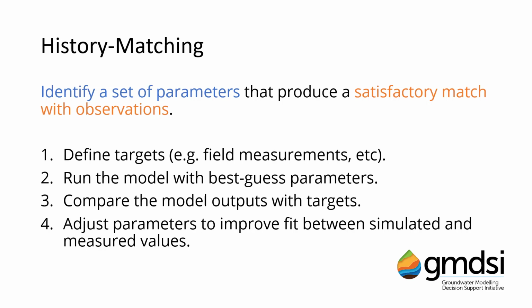and repeating the process. In essence, this is what you would have done during assignment 2, in which you perhaps manually adjusted hydraulic conductivity and maybe recharge to match measured values of head with which you were provided. This is what is referred to as manual trial and error.